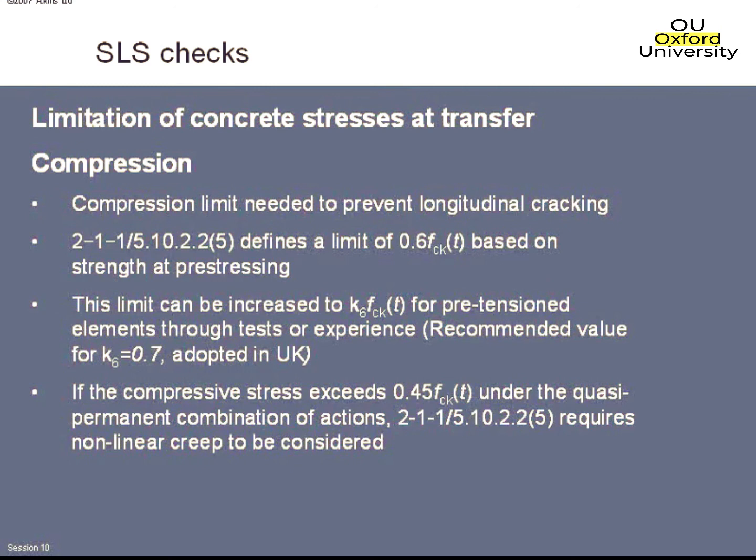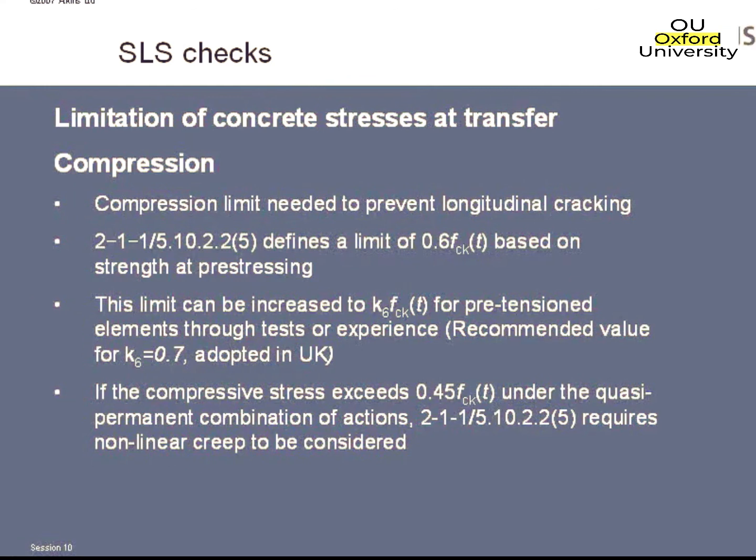And then there's just a reminder here that although this isn't a limit in compression, if we increase our compressive stress on the section to more than 0.45 fck, then we do need to consider this nonlinear creep, which could be quite onerous.